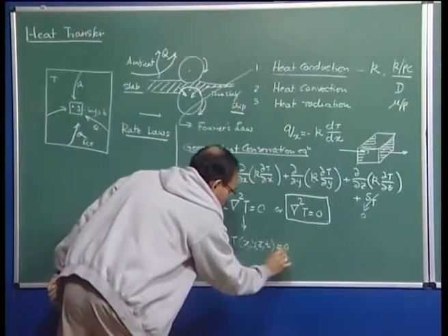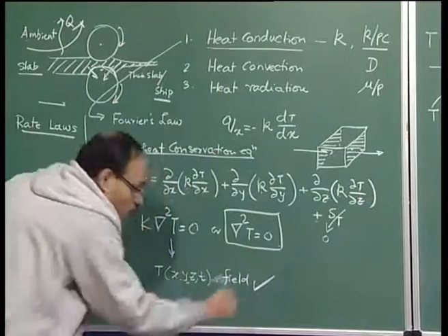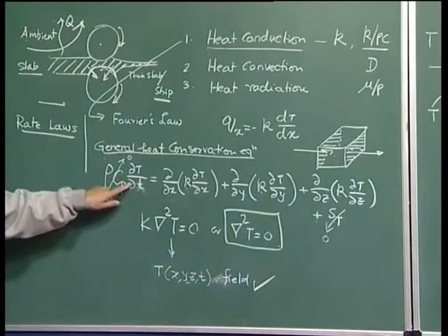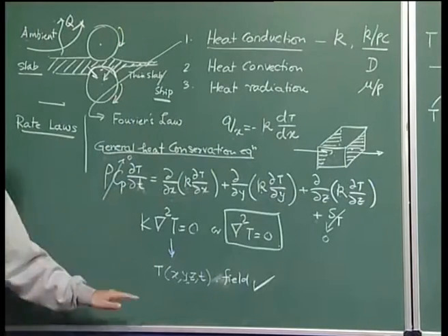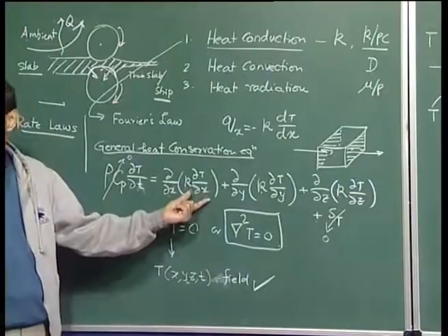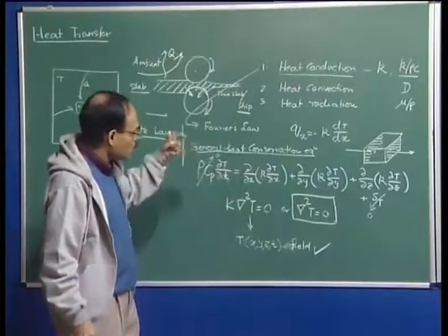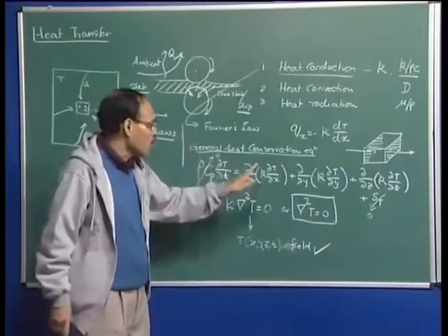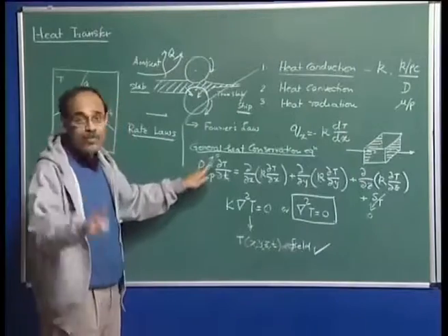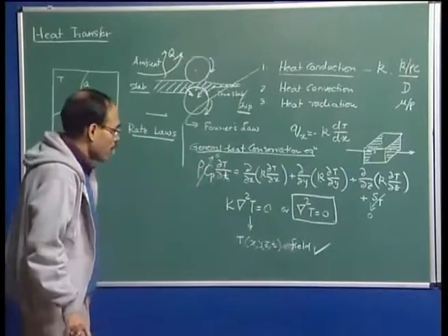This is now known to me. So I have the governing equation, boundary conditions are there, and I have solved this. Again, I would repeat that we cannot solve it analytically. We have to solve it through numerical techniques. Assuming that we can solve it, it is one equation, one unknown, given the thermal conductivity, the source term, and the properties. The unknown being T, which is called the dependent variable.